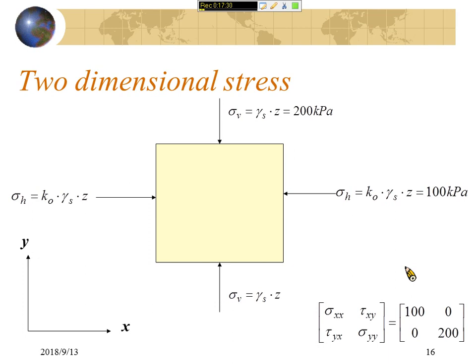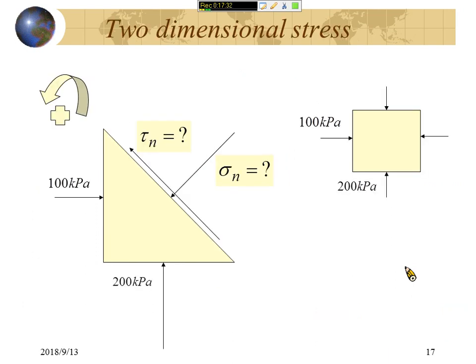Okay, so I want to know what is the normal stress and shear stress acting on that plane. How to solve this problem without the help from Mohr circle? You can start from the very beginning. You can try to solve the equation for the force equilibrium. Then you can solve this problem. But please remember, it's force equilibrium, but not stress equilibrium.